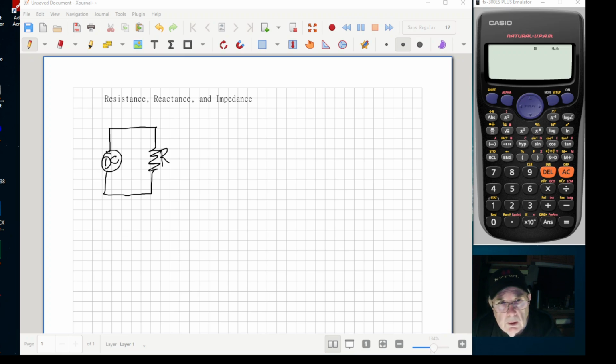Okay, in this video we're going to talk about resistance, reactance, and impedance. The first thing to understand about them is that they are all opposition to the flow of electrons in a circuit. And perhaps the easiest one to understand is resistance in a direct current, DC current source. This is where the current flow is at a constant rate. And the resistance is the opposition to that, and the energy that's lost is oftentimes given off as heat.